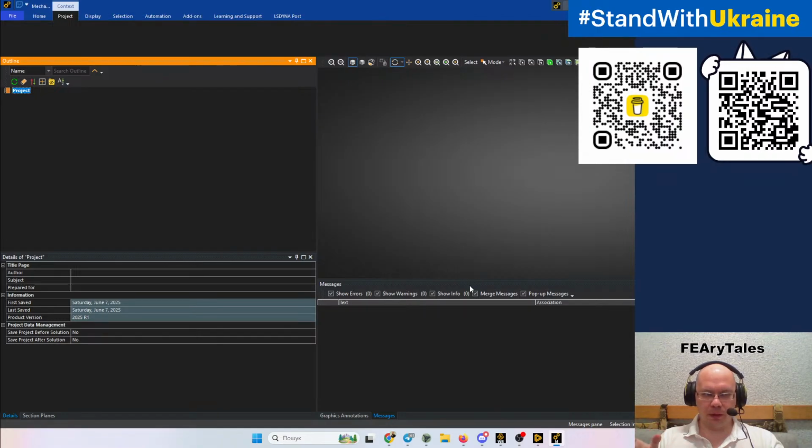Import those files, open them with Discovery, and only after that open Ansys Mechanical. With this type of workflow, when you first open in Discovery or SpaceClaim and then open in Ansys Mechanical, you will have the same IDs already.